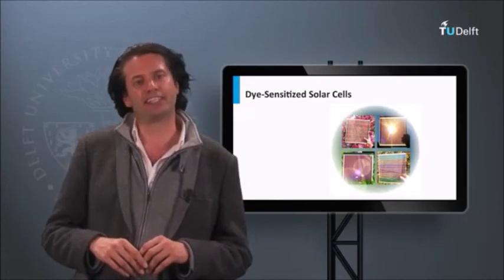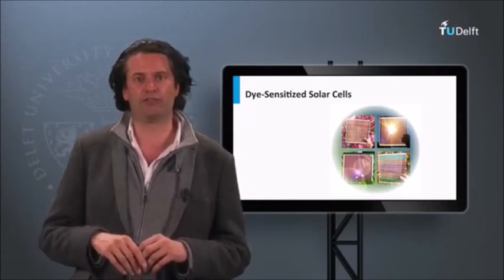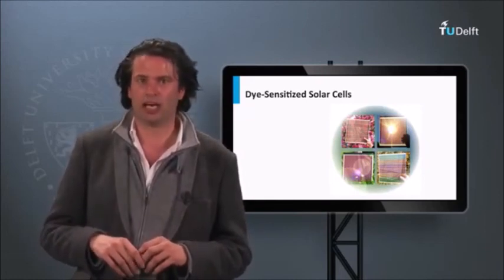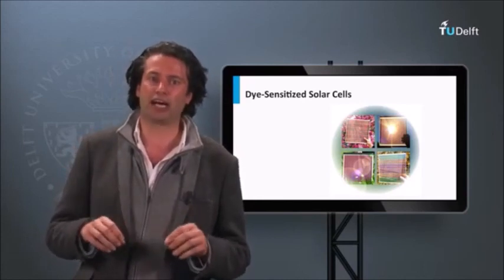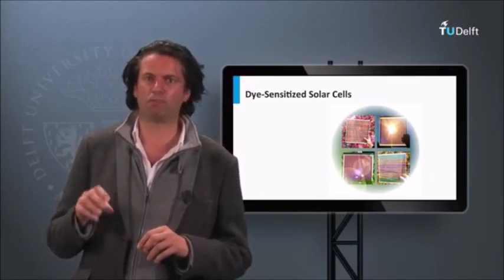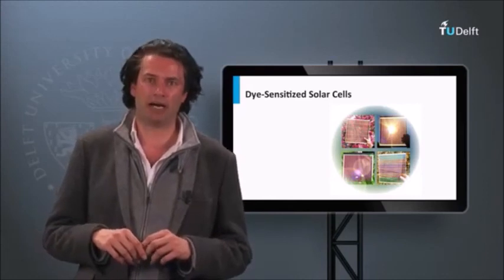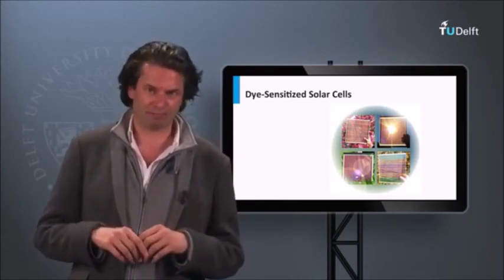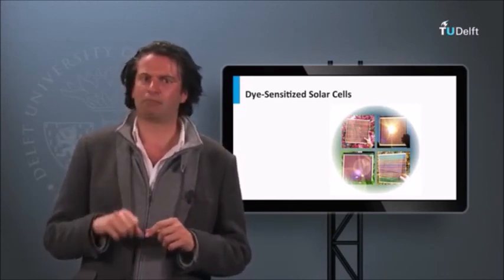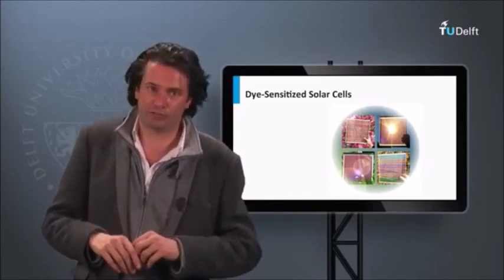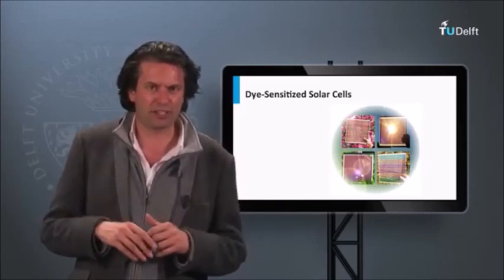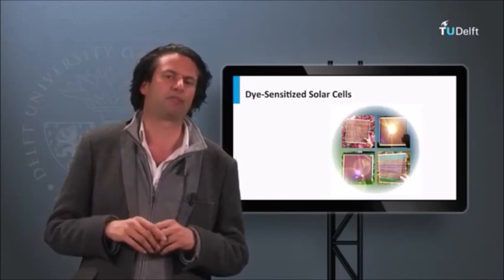A disadvantage is the stability of the electrolyte under various weather conditions. At lower temperature, the electrolyte can freeze. This stops the power production and it might result in physical damage. Higher temperatures result in significant expansion of the electrolyte, which makes encapsulation of modules more complicated.